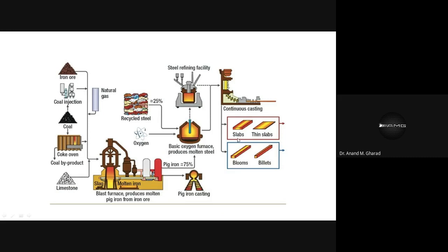Yes, sir. Okay. So whatever members or structures I have shown you in the picture are hot rolled type of sections. Hot rolled means it is a process which is followed after the formation of these outputs. What is done in hot rolling, as you can see, the thin slabs or thick slabs or billets and blooms are actually still hot.